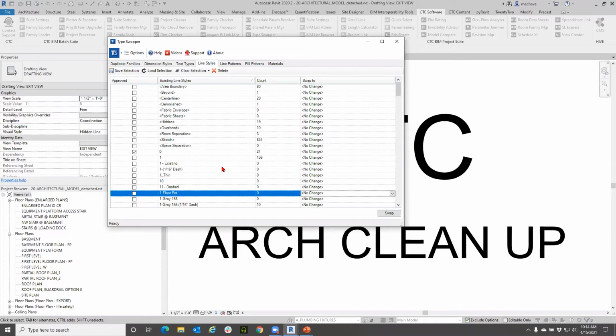Maybe you're transitioning from AutoCAD to Revit. You have some details you want to bring in. Always bring it into a proxy project. It's not supposed to be brought into your actual working project, right? That would then be allowing you to then do whatever you need to do with that AutoCAD detail and transition it to more of a drafting view for Revit purposes.